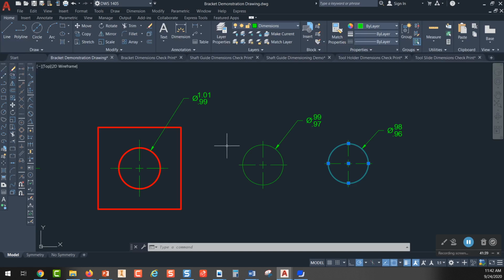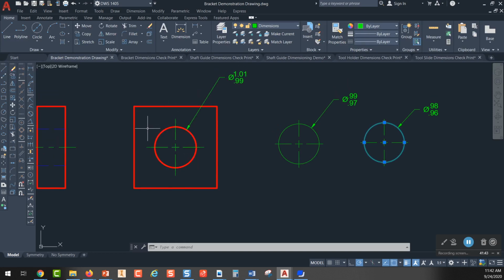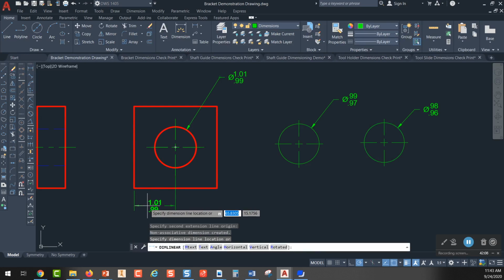All right. Now, I want to show you something else about tolerances on this part right here. This seems like a really simple part, but we already know that the diameter of the hole might not be exactly 1.00. It could be 1.01 or 0.99. But I'll show you something else that's weird about this. Let's say that you're trying to locate the center of that hole, and you measure from this datum feature over here, and you measure to the quadrant.